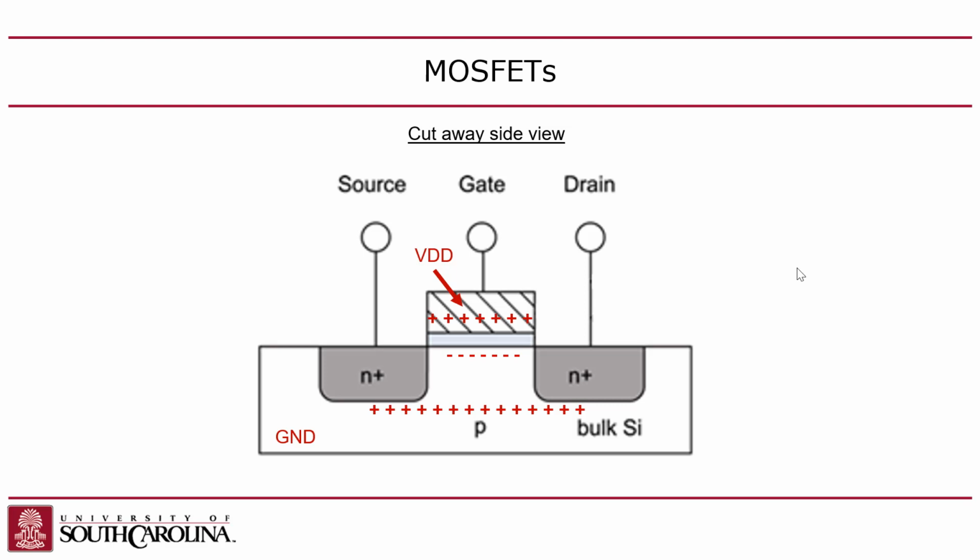So now the problem here, though, is there is an issue here, because I told you before that the substrate was grounded. So you might think, okay, well, here's a capacitor between the grounded substrate and the gate, right? But the problem is that when these charge carriers accumulate in this channel, they become their own thing.